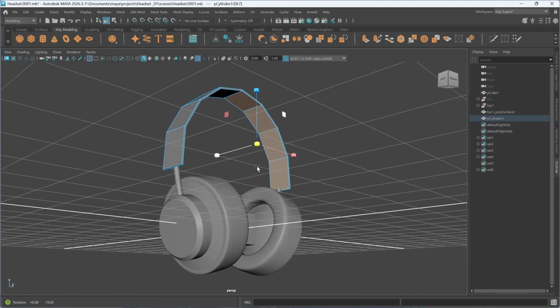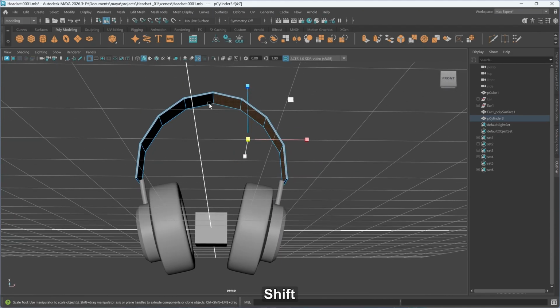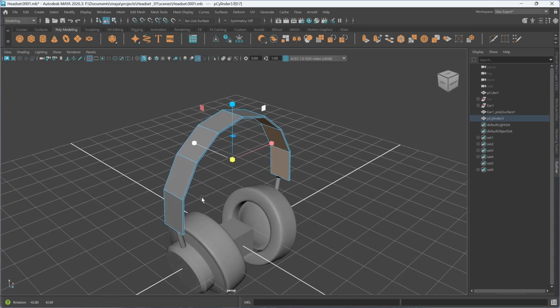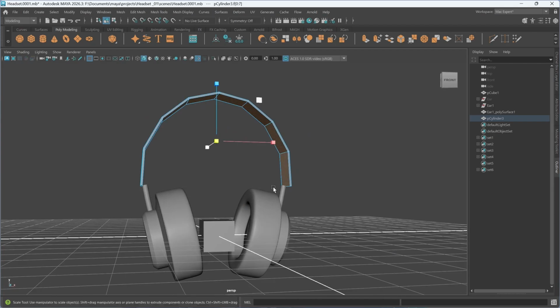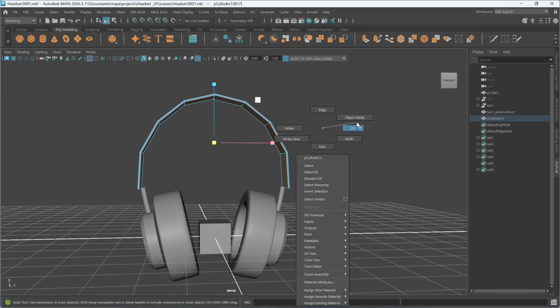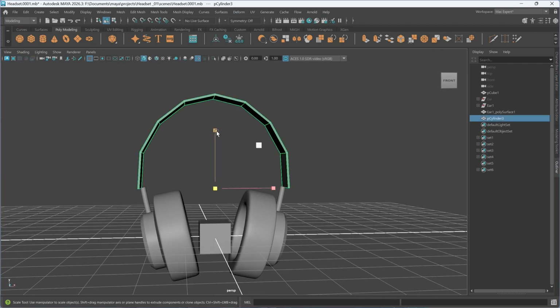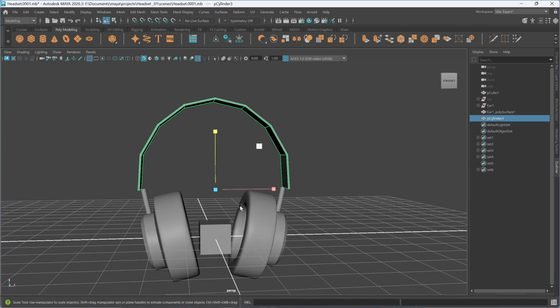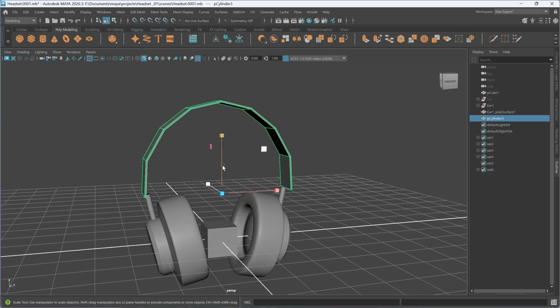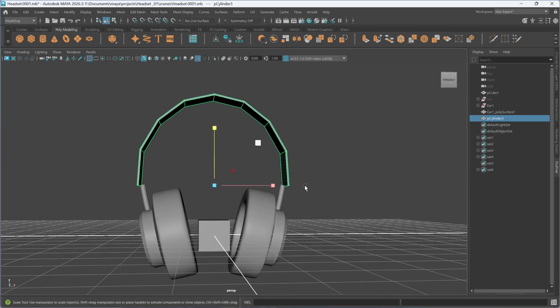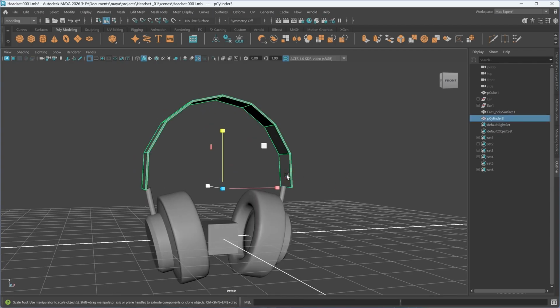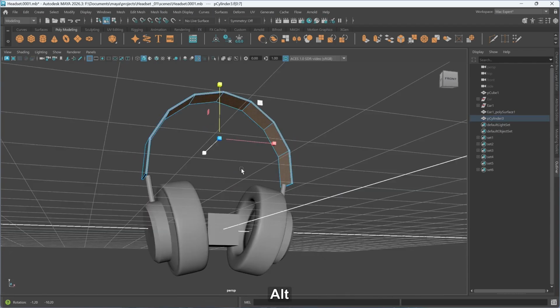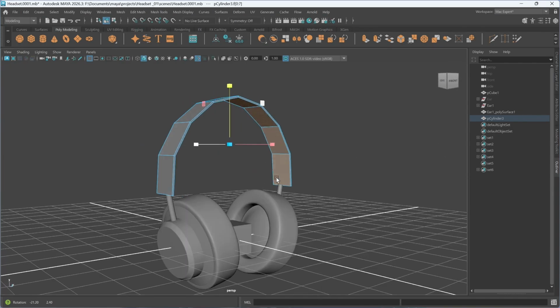So we're going to leave it that way. And we're going to select this. So this is extending. Now we can go into the object mode and just scale this down a little bit, because this is also extending. So we can work with it that way. Maybe just a little scale. Yeah. So we'll go into the face mode, and yeah, we're done selecting the loop.